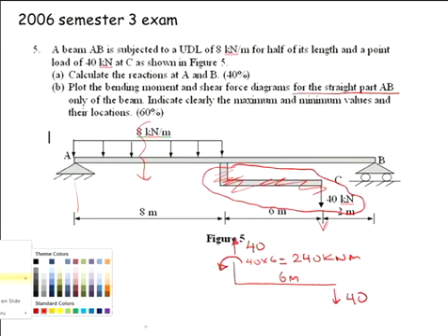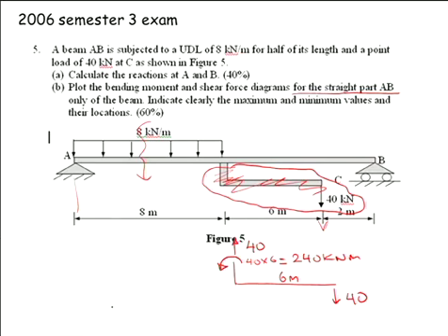So if I want to consider that dag hanging off there removed, I would say, okay, well therefore I'm going to put a 40 kilonewtons here, and as well as that, there's a moment applied here of 240 kilonewton metres. So they are in effect the resultant forces that that beam AB experiences.